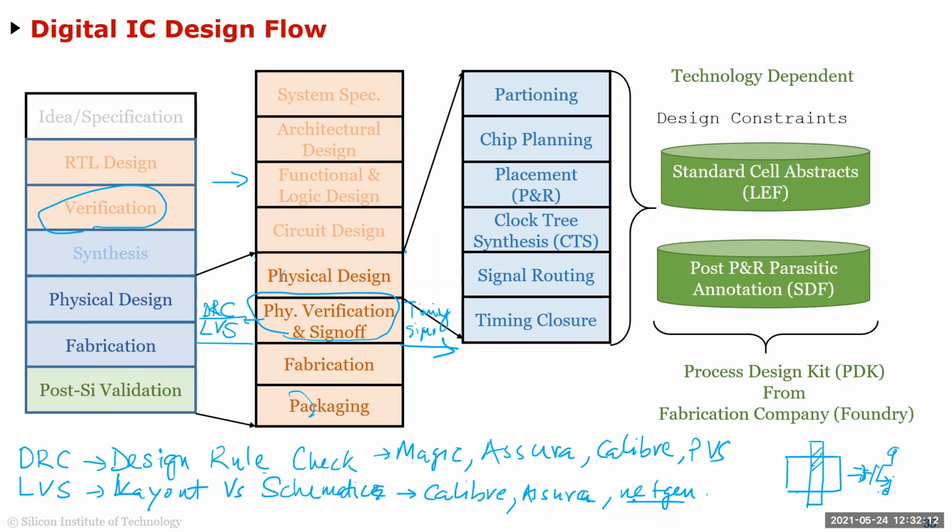So basically it is saying that the process is going to change. So I told you, right? A wafer is going to come out and I'm going to have 1 million devices. Now that inverter might have 100 picosecond for those 1 million devices. Tomorrow I go and order, a wafer comes out, I get 1 million chips, but now it is 90 picosecond because those are the variability of the process, which I have to design within. 3 years later, I order another 1 million chips from the foundry. It comes and I found that it's actually 200 picosecond. Okay. So I have to design for the maximum.